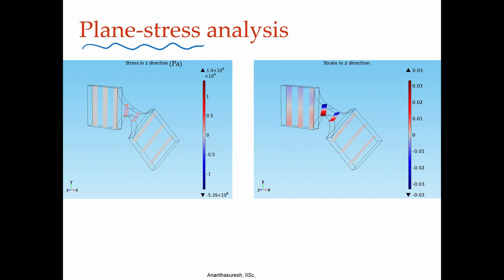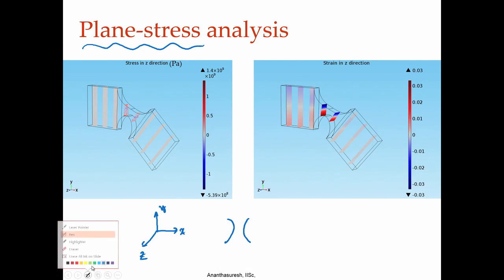Okay. But if you take a 3D thing, you have to have a lot of elements and a lot of degrees of freedom, and computation takes more time, but this structure is essentially planar. It is an extruded section, nothing changes in that direction. So, you can use 2D analysis. There is something called plane stress, and what that means, plane stress condition, is that if I were to indicate the axes, let us say x and y, and z is out of plane. Let us say my structure here, that is the circular flexure that we have, is horizontally drawn.